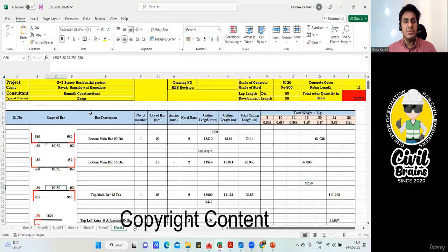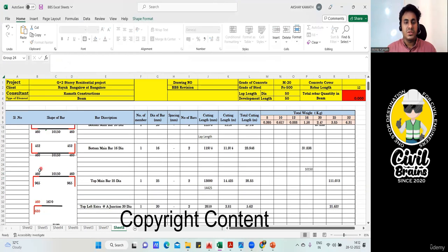So same thing I've done here. 5525 plus 5125 minus 250 from here minus 250 from here. I'm going to get clear span, that is column inner to column inner. Done. So that is 10,150. Again, this remains same. 500 minus 40 from here, 500 minus 40 from here. So it is 460 and 460. Agree with me?